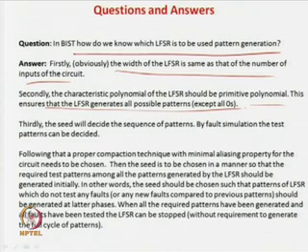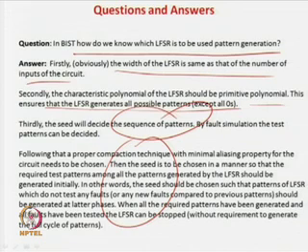Thirdly, the seed. The seed is very, very important, as I told you. You have to generate the seed in such a fashion so that the initial patterns can do your testing for the coverage. Following that, the compaction technique. You have to find a good compaction technique. So, what is a good compaction technique? That which is going to give a minimum amount of aliasing for the set of patterns which you have decided using this LFSR and the seed.